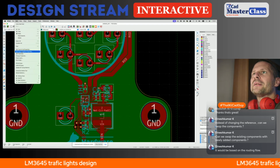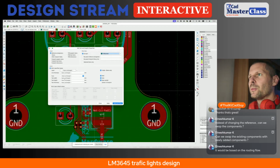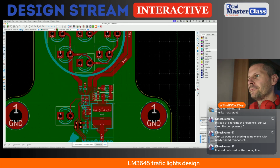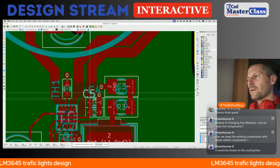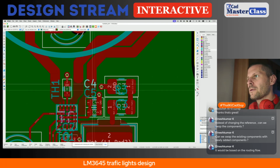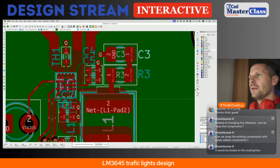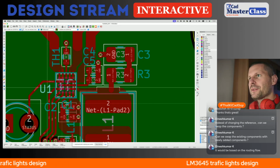and now I am editing all the resting reference designators in silk screen layer to be 0.7 in width and 0.7 in height and 0.1 in thickness. So this is the NTC snubber components. Here is decoupling capacitor.